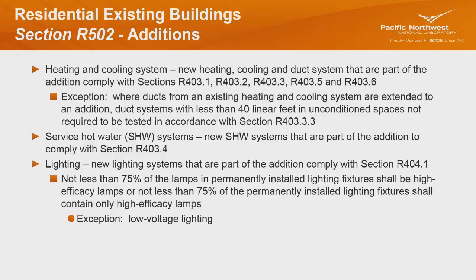There is no ductwork or duct design that you would enter in either software tool, REScheck or COMcheck. It's actually a checklist item, and so is duct insulation and duct sealing and duct testing. But this exception is if you are adding less than 40 linear feet of ductwork in unconditioned space, then it's not required to be tested. It still has to be insulated, still has to be sealed, but the biggie is that 40 linear feet is the threshold that you wouldn't have to retest the duct system.